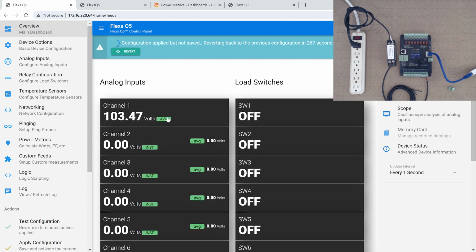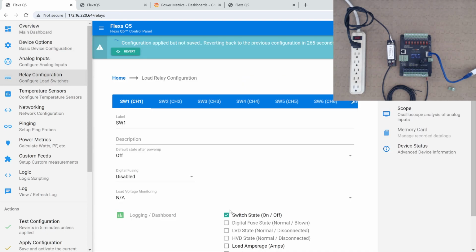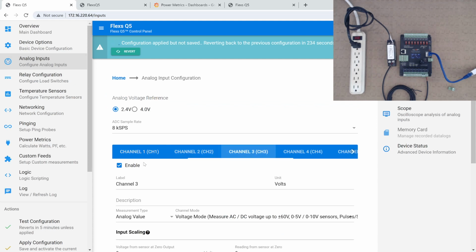And so that's good. We could clean this dashboard up a little bit. We don't need to show all of the relay switches on there. And all of this data, the voltages, power consumption, power factors, could be made available via SNMP, via Modbus TCP, via JSON, via RS-485 serial port. Whatever you want to do with this, this data is easily integrated with whichever platform you're using.